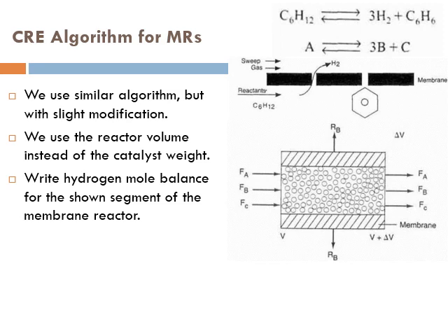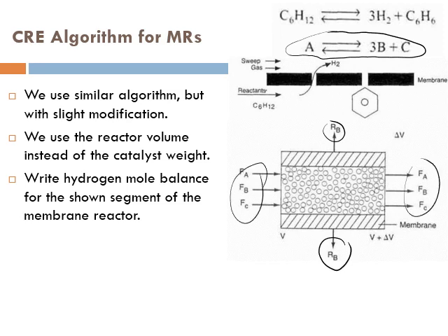Okay, and in the middle of the reactor we have this reaction taking place. A is being cracked to B and C, where only B is diffusing through the wall. So we have a mixture of A, B, and C here, and then a mixture of A, B, and C here, but some of B is diffusing out, and the reaction is taking place here, and more B and C is being generated, and more A is being consumed. So let's do a material balance. Of course, you know that if we're doing a material balance on hydrogen, which is B in this case, the number of moles of B or hydrogen is not conserved, right?